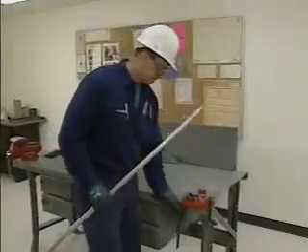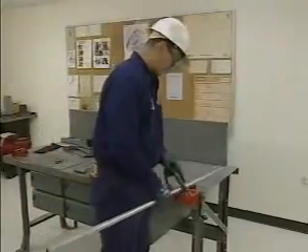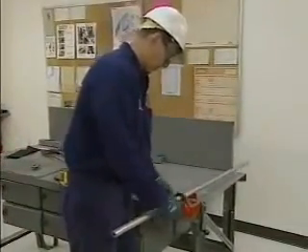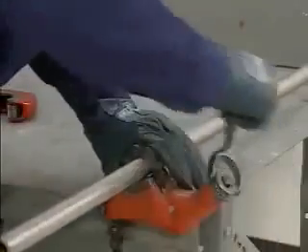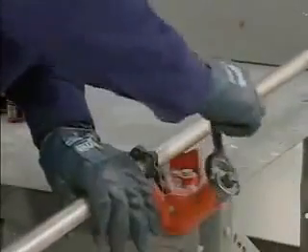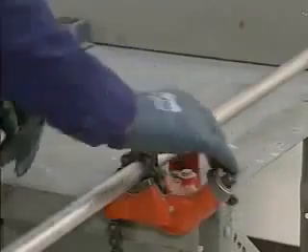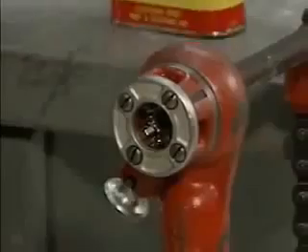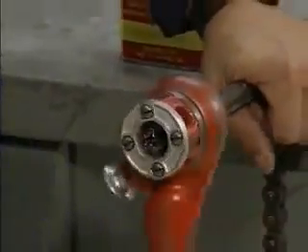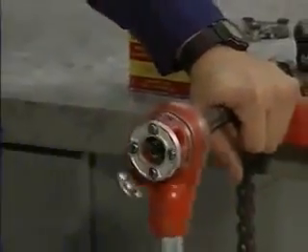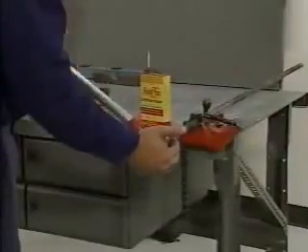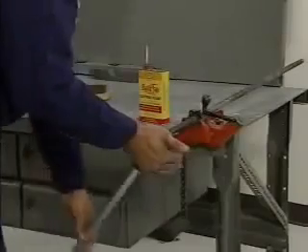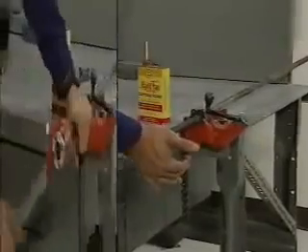Pipes can be threaded in different ways. Electric pipe threading machines may be used, but we'll use a hand-operated pipe die as an example. There are a few basic steps to hand threading a pipe with a pipe die. First, you should secure the pipe in a pipe vise and apply cutting oil to the end of the pipe. This provides lubrication and reduces the heat that's generated when the die cuts into the pipe. Next, press the die against the end of the pipe and turn it clockwise with a ratchet handle.